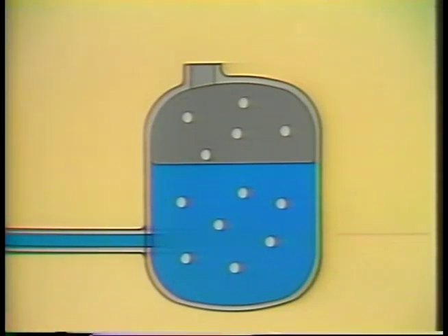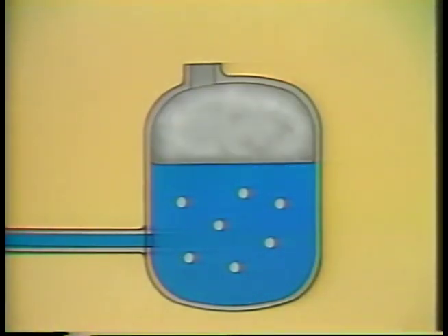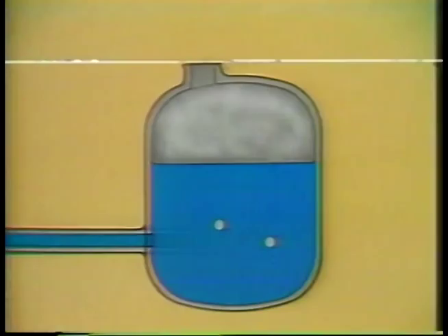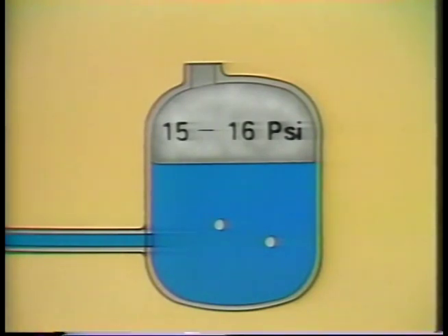If the air at the top of the tank is displaced by a blanket of steam, then the amount of oxygen absorbed will be greatly reduced, and corrosion to the tank and to plant systems will be minimized. Typically, a steam blanket will exert 15 to 16 psi on the tank. This means the total pressure in the tank is a result of two factors, the steam blanket and the height of the water. To determine total pressure, we would add the two factors.